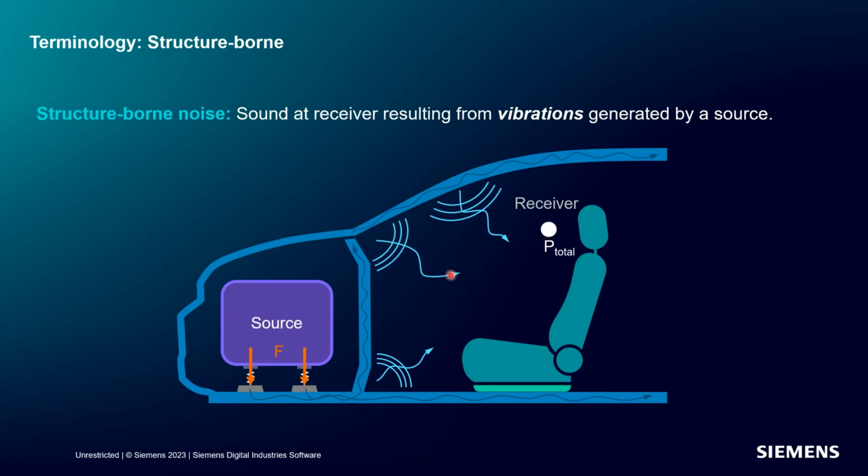except instead of going airborne, it would just go through the structure and vibrate it. We would maybe measure vibration at the seat interface, and that would tell us how uncomfortable the vehicle is for the operator. And even that vibration target could be caused by an airborne source. So if this motor was loud enough, it vibrates the structure and then creates unwanted vibration at the operator interface.